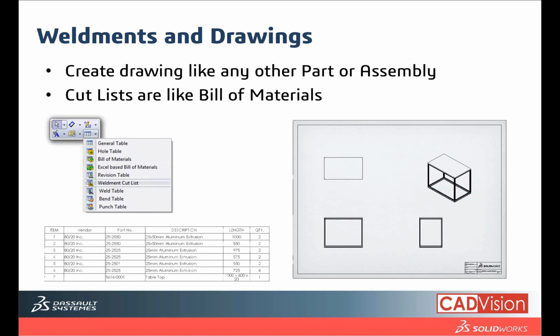So it's the same old procedure as how you put your parts into your drawing. Simply click on the drawing palette on your right hand side, or you can just insert drawings or insert model views into your drawing. What I like to do is click on the drawing view and then just drag and drop into my drawing. Once I have all these parts, I have all these drawing views.